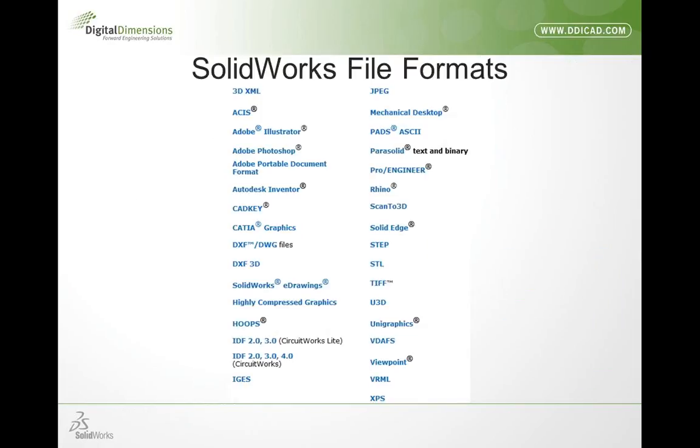So anyway, SolidWorks can basically interact with all these different file formats, and they do in different ways, and it depends on different versions and stuff of some of these. So there are some restrictions to these, but for the most part, this is pretty much the summary list of what file formats are available to either import or export in SolidWorks. Our most common ones, as far as universal file formats, are going to be for the 3D type stuff. The Parasolid, Step, and IGES are probably your most common ones. You'll see almost every CAD package out there have an ability to do one or all of those. And then DWG, DXF are going to be your 2D common ones.